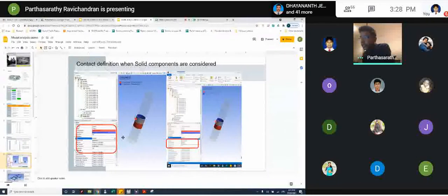Usually, Ansys has an option of automatic detection between those bodies. Sometimes it would not properly be able to contact between those immediate surfaces. You have to make sure those surfaces are not interacting because they would consume additional analysis time.